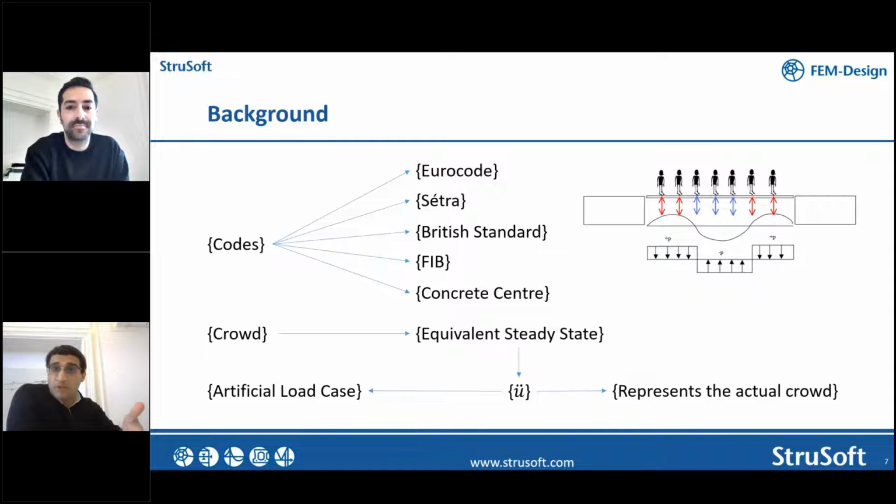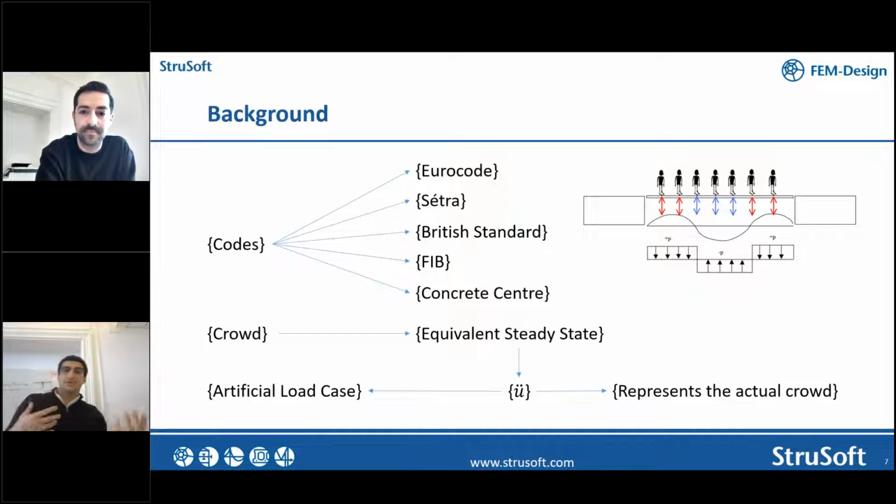So if you compute the modal load, in a continuous formulation it's the integral of the modal load, and you would like to maximize the action. And when you do that, you come up with the same SETRA approach, which is following the mode shape. As long as you follow the mode shape, you are maximizing the modal load applied. That is, in your projected single degree of freedom representative of the mode, you maximize the applied projection of the load. That is your modal load. And this is done by applying a force that follows the motion.